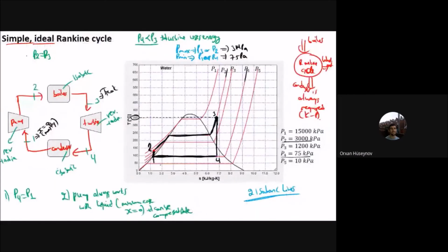Wait, the 10 kilopascal line is this one. The pump, the turbine, the peak temperature doesn't change, only you are moving the line here. Therefore, the pump will supply the energy from 1 prime to this position here, this 2 prime.